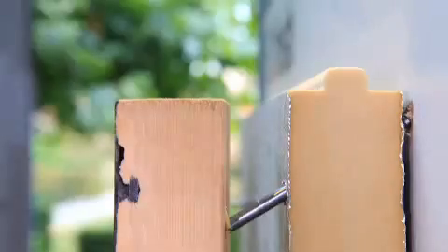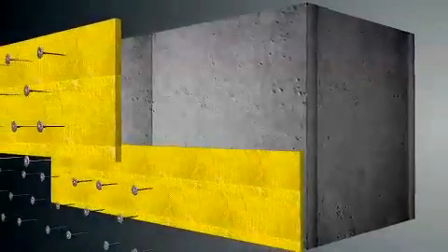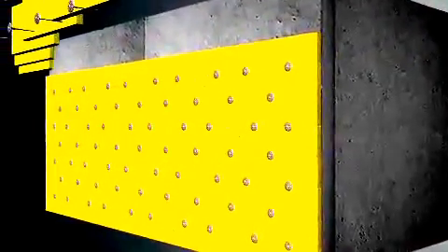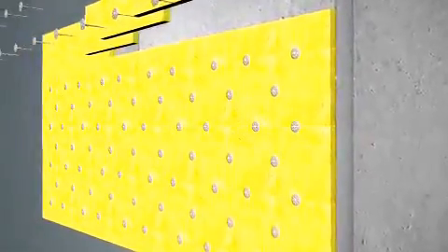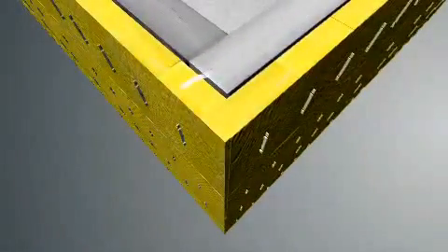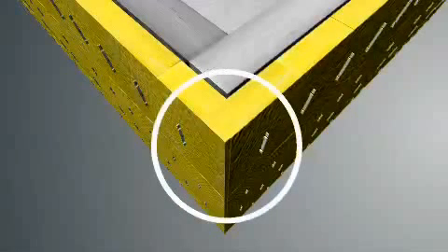To meet these criteria, a number of insulation suppliers have a board for ventilated facades. Whichever insulation board is chosen, they must all be securely fixed to the structure, which is normally with special fastenings. Over time, the insulation must not sag or bulge out to block the air cavity. It is important that the insulation has no gaps at its joints and fits tightly around the subconstruction to reduce heat loss and the effect of cold bridging.